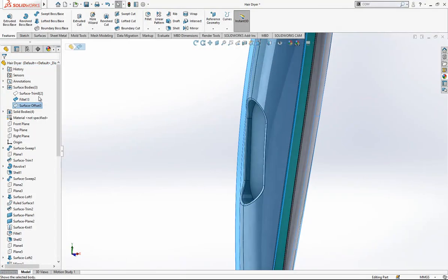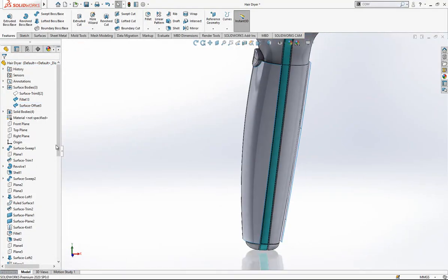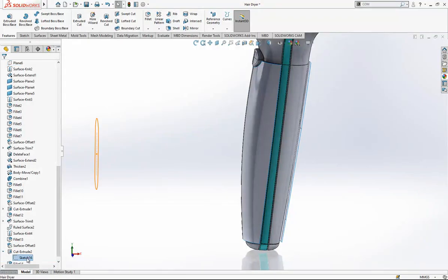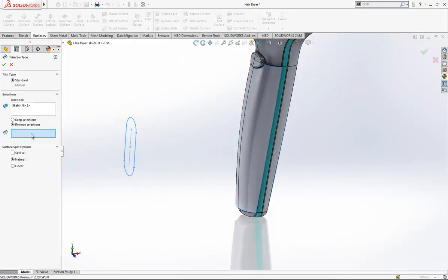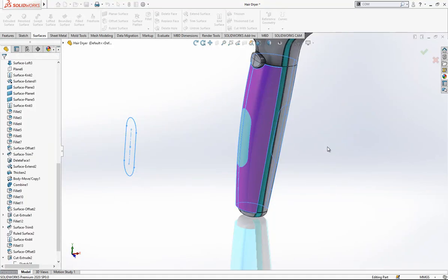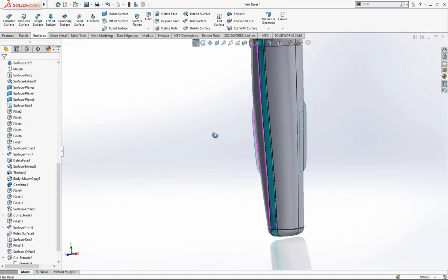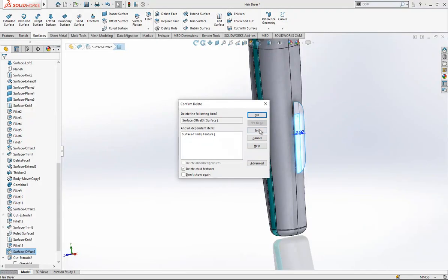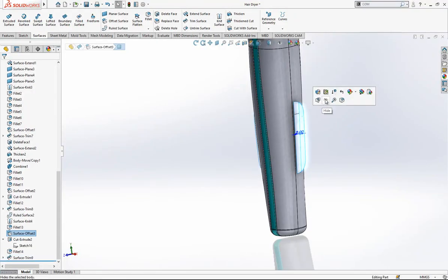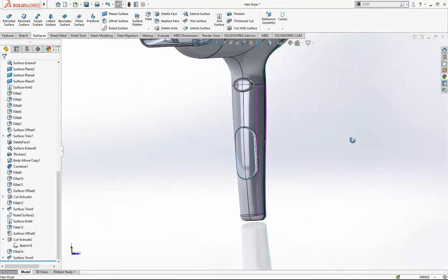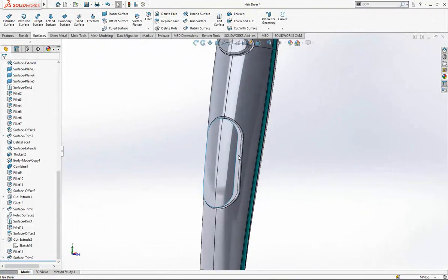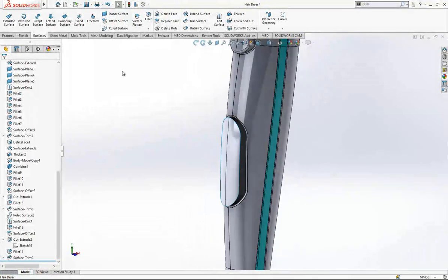And here there is a surface body, which is 2 mm offsetted, and then we will protect that one with trim, remove. Okay, this is also unnecessary because if we didn't make a mirror at the other side, that surface completely copied. And this is looking nice now.